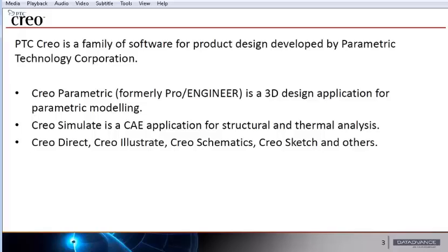Now I'll try to answer the question, why we need pSeven if PTC Creo has its own solver, I mean Creo Simulate, and also has some embedded optimizers. So why do we need integration if all calculations can be performed inside Creo itself, and why do we need all these algorithms also? The answer is that these embedded capabilities are not enough. Generally, embedded CAE, like Creo Simulate or SolidWorks Simulation, are tools for quick and preliminary analysis. When solving real problems, external solvers like Ansys Mechanical are usually needed. It's especially true for multidisciplinary problems, which may contain, for example, strength analysis, thermal and gas dynamics, and other calculations that have to be bundled into a single model.